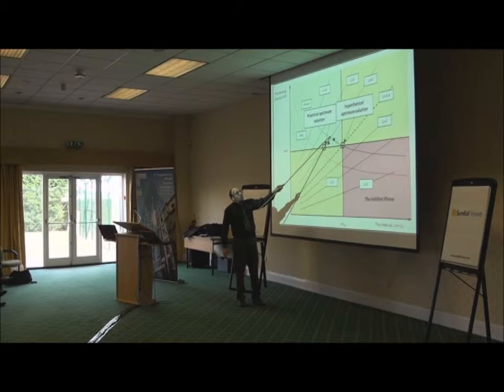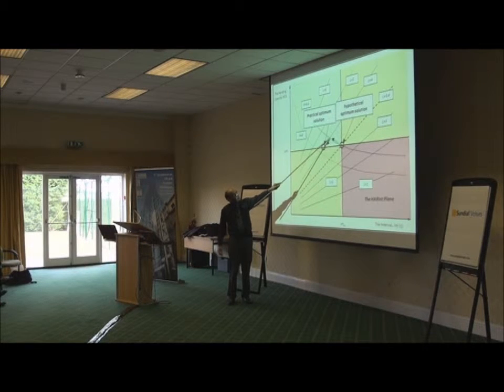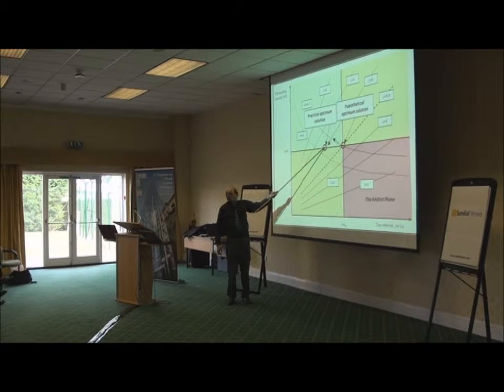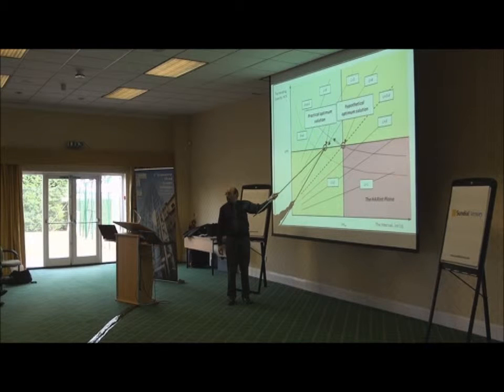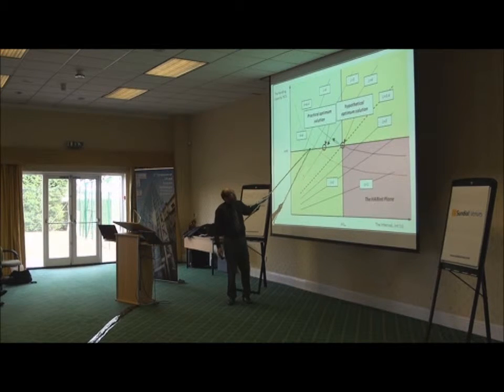Once we round up from 3.4 lifts to 4, we move up to this point. And then obviously we will go back down and settle on the AR line. And that's the difference. I mentioned this last year. For those of you who use Elevate, this is the difference between up peak and enhanced up peak. You just end up on 12%.